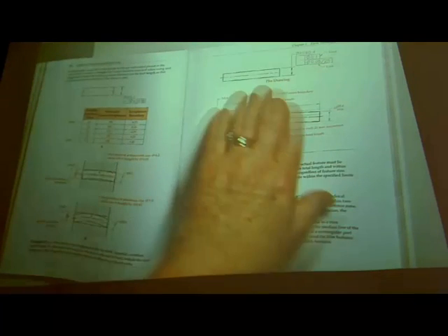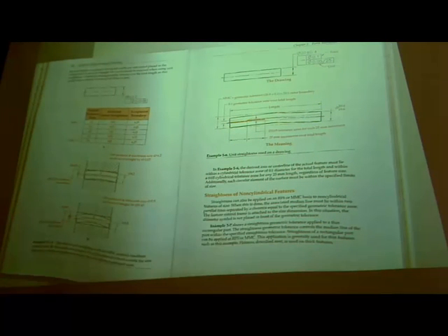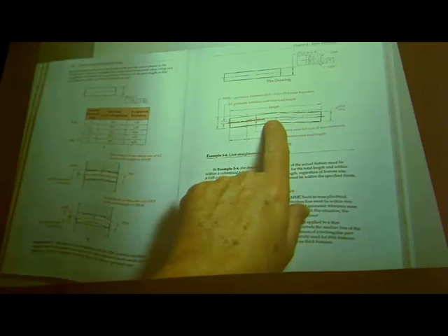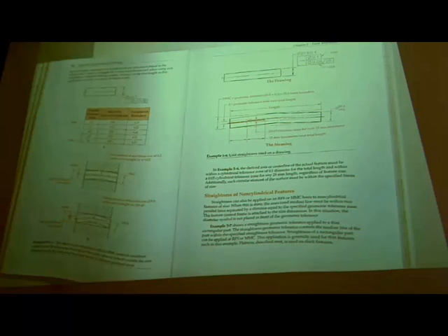All right, unit straightness then just breaks it down per unit, per length, and you're saying it has to be straight in this area, right? Notice they're exaggerating here and showing us that overall there could be a kink in the part. You have to allow for that. You have to be careful that you don't leave off a whole length straightness that should control it overall.